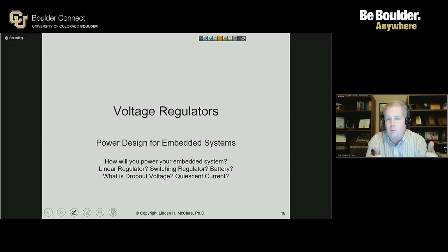But not all chips will give you that, and once you start putting multiple chips together, then it becomes a little bit murkier because maybe you don't need one capacitor for every chip. Maybe if you've placed your chips closely enough that one capacitor can serve more than one chip, and therefore you can do some optimization that way. In that case, the data sheet gives you part of the story, but not the whole story.